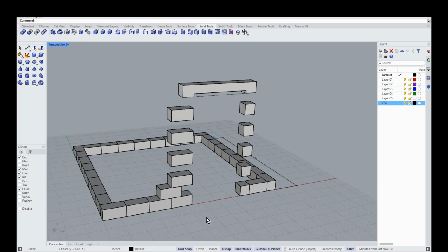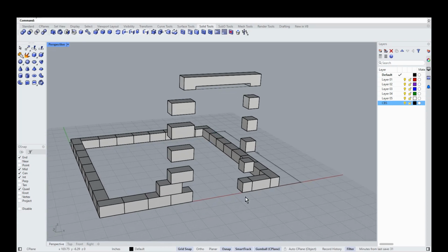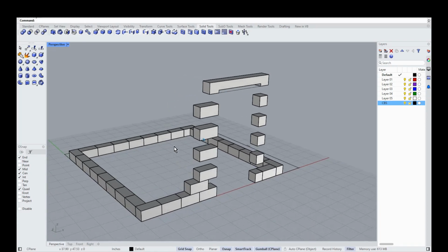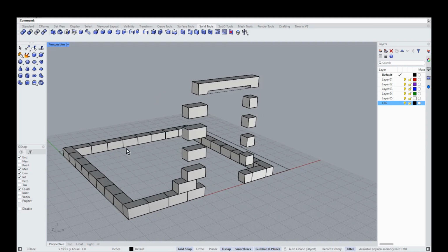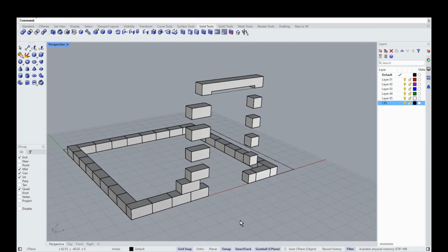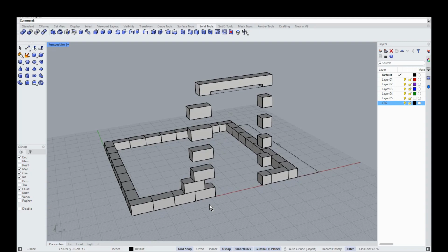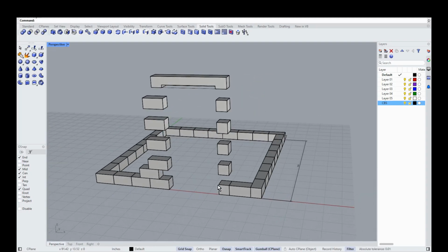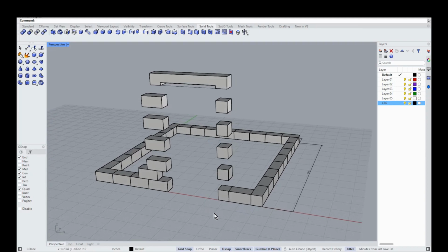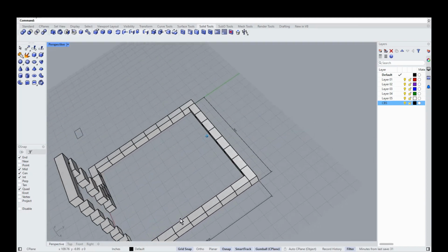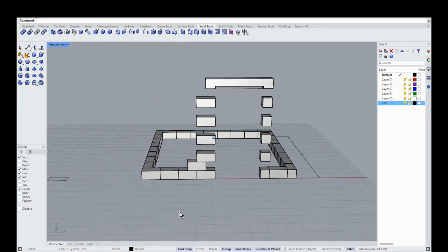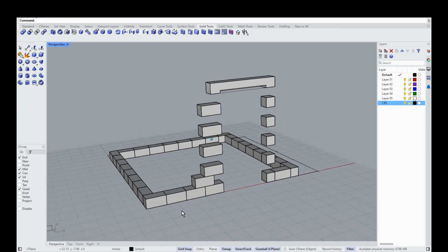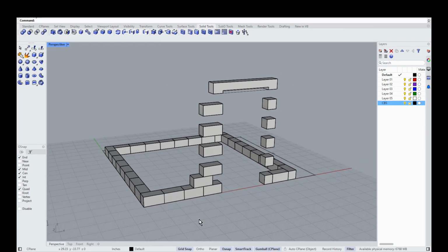And those can often jive with the block course, the 8-inch block course. They'll put bucks around windows typically to attach them to. That's usually pressure treated. And again, this is all southeastern United States kind of construction, but it goes to show you the factors to look at, what to consider when doing this kind of stuff. Hopefully, this will give you some new tools if you're an architect, if you use Rhino. Rhino's very popular with architects.